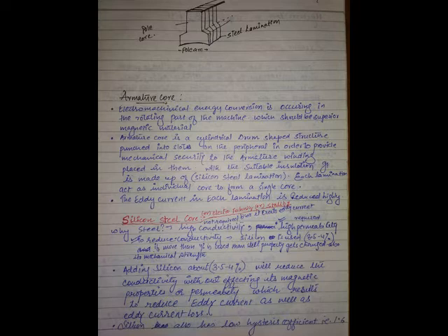So on this commutator, if two segments are short circuited outside, immediately inside the armature, two coils are short circuited. So the commutator plays a vital role in collecting the current, no doubt. Anything that happens on the commutator directly reflects onto the winding. So while collecting current from the commutator, it should be as sparkless as possible. We'll discuss these points.